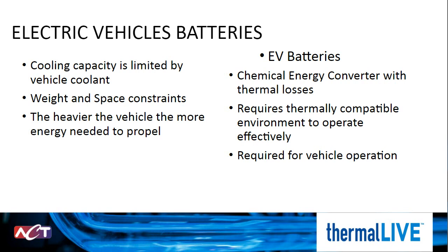Since these factors cancel each other out, there really is a temperature zone for a battery to operate efficiently. And this will vary based on the chemical composition. So typically, a lithium-based battery will operate most efficiently in the 20-25 C range. So an electric vehicle battery designed to hold the temperature at 25C plus or minus 5C will be able to provide a vehicle with higher efficiency and therefore a longer life.